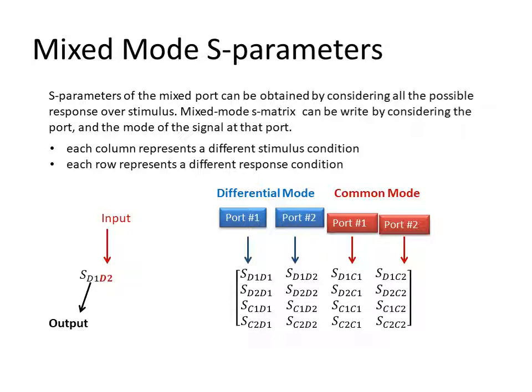But for the analysis of the circuit, we first use the symmetry of the circuit, then divide our circuit, we draw a symmetric plane. Then this particular symmetric plane is virtual ground and virtual open: virtual ground in the case of differential mode and virtual open circuit in the case of the common mode.